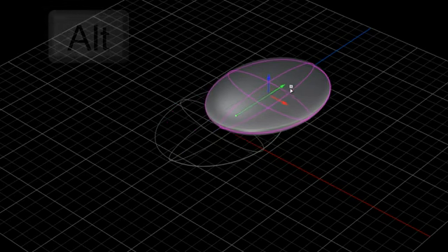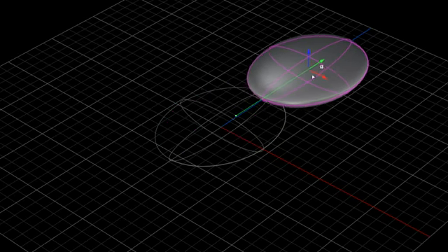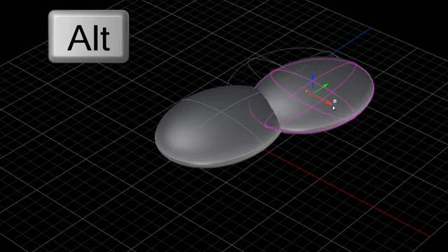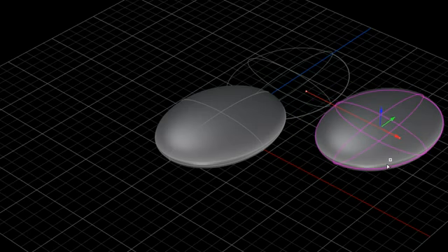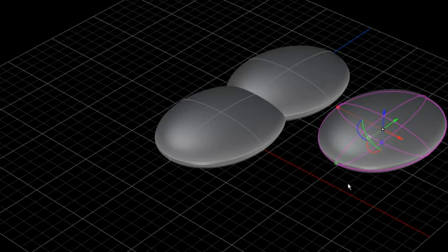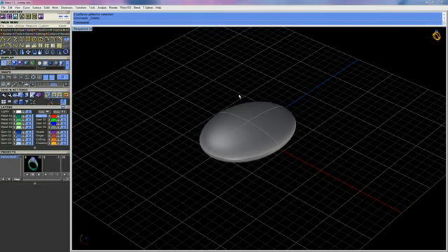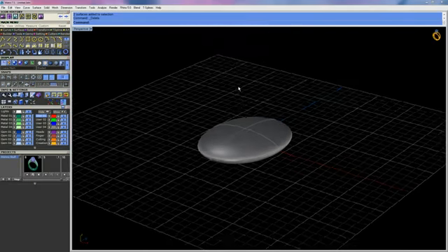once you hit Alt, you'll notice there's that plus sign right there. Okay, so a simple tap of the Alt key versus holding down the Alt key is how you get your copied object. All right, so that is a slight difference in the new version of Matrix in Rhino than you will be used to. So that is an overall look at our gumball.